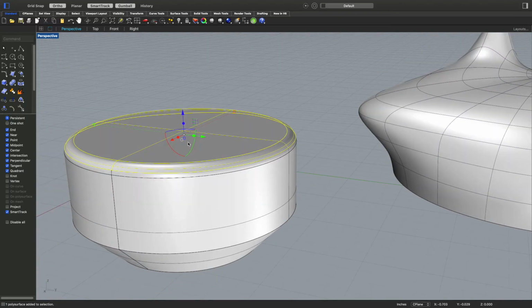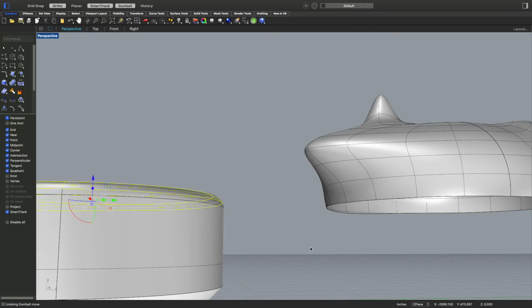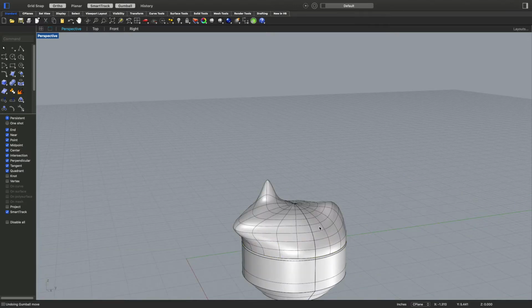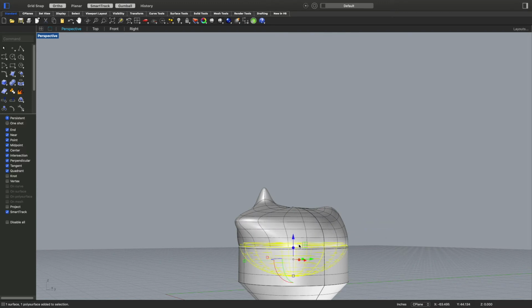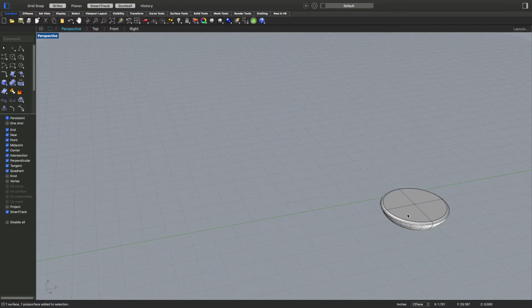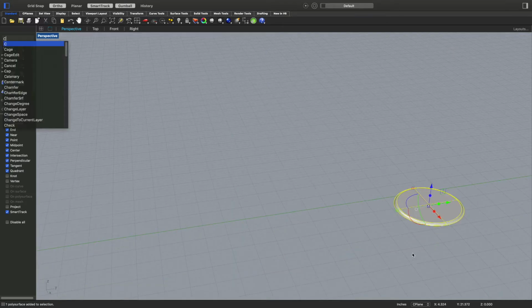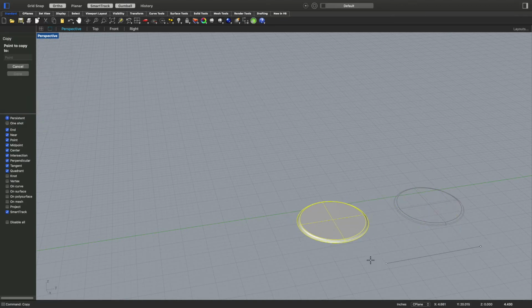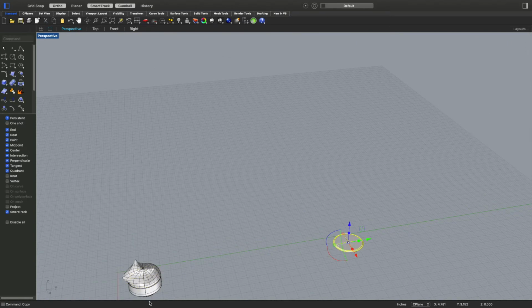give us a little spot that we can use to close off this bottom. Get it? So let me undo twice. And I'm going to copy this part. I'm going to go from left to right here with my selection tool to grab both of these bottom parts. I'm going to move this 20 inches that way. Delete this bottom part and move and copy this 20 inches that way. And click to end the command.